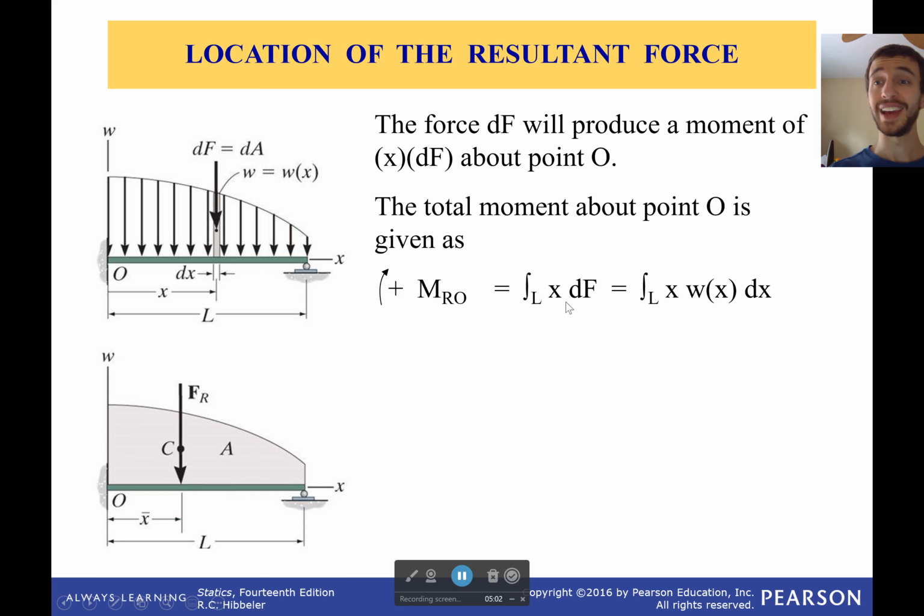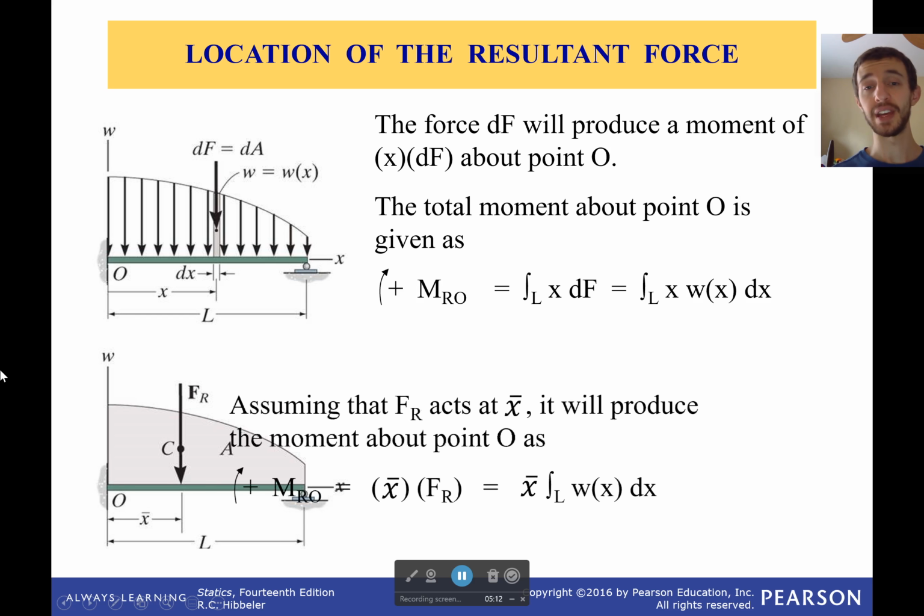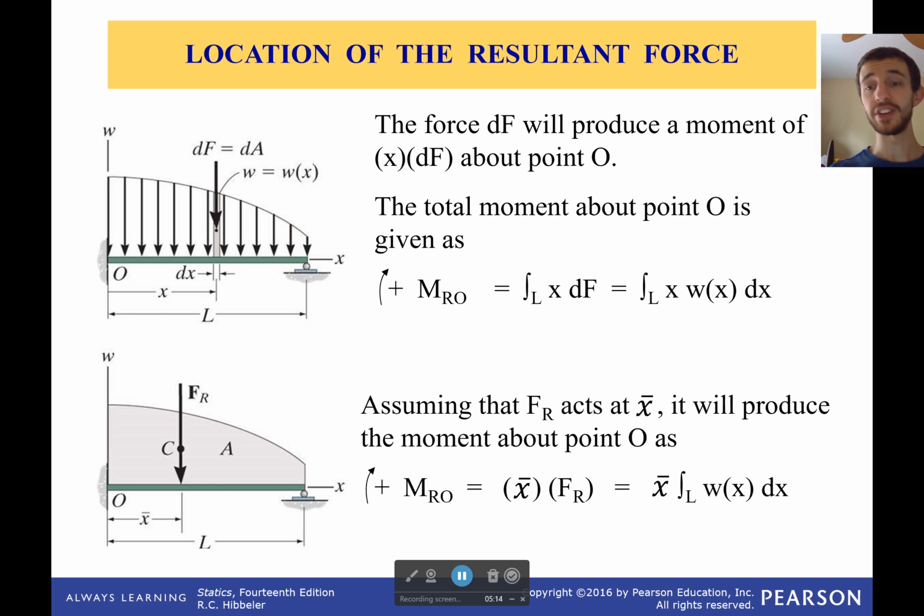resultant moment. If you remember, when we have a resultant moment and a resultant force, we can figure out the distance to where that force could be applied to have the same external effect. This is actually just solving for the centroid, okay? The resultant moment is going to be equal to our centroid, how far we have to go to get to our centroid, times our resultant force.